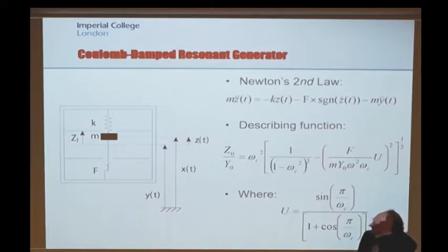So when we looked at the initial equations here for the piezo and putting a resistive load onto the piezo, we said it looks like a linear system in the sense that there's a damping which is proportional to velocity, and then there's a small tweak to the resonant frequency. That is the behavior of the system with a resistive load.